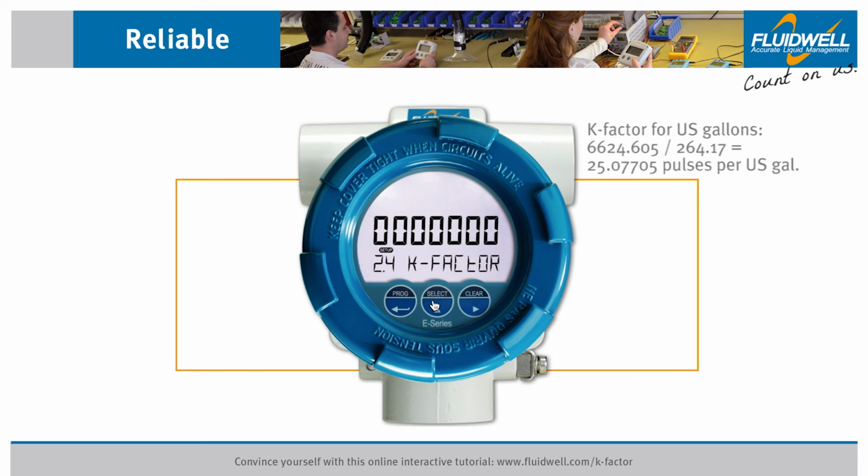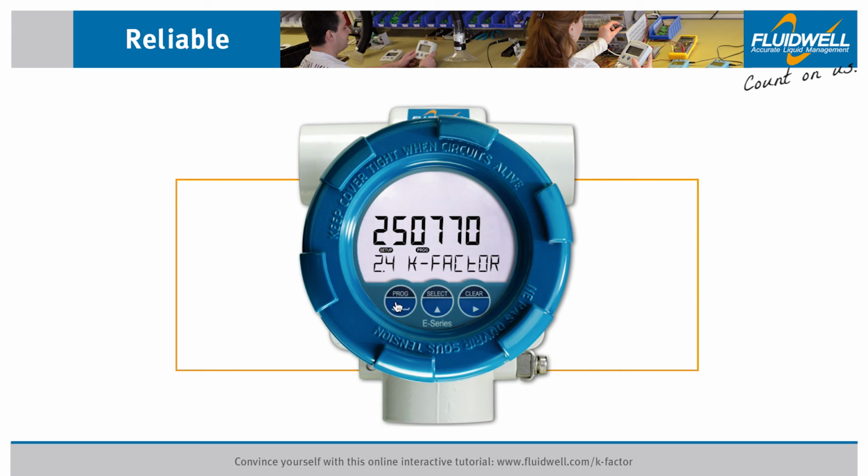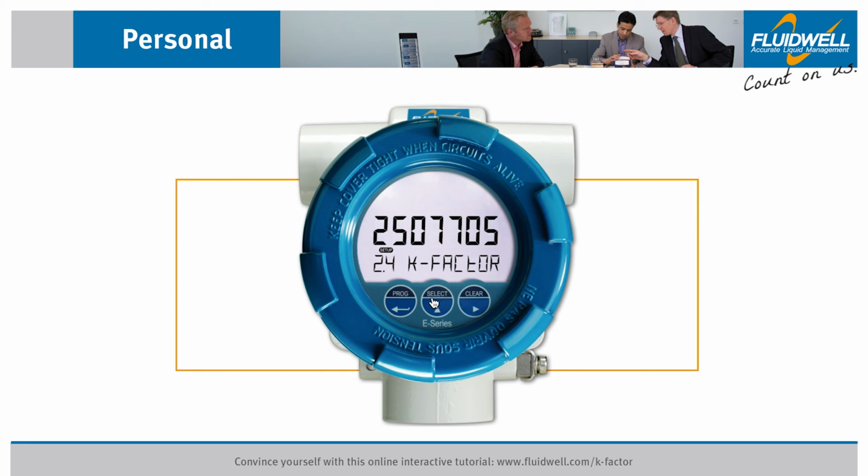We are going to set the K-factor to 2507705. The amount of decimals is not set yet. Press Prog to store this setting. The next step is to set the decimals for the K-factor. Press Select to go to Menu 2.5 K-factor Decimals. Press Prog to change this setting.